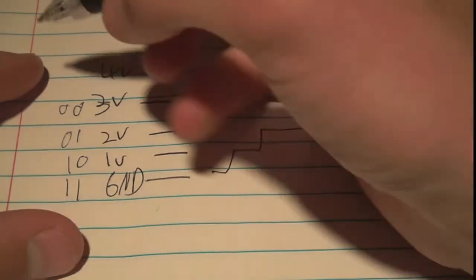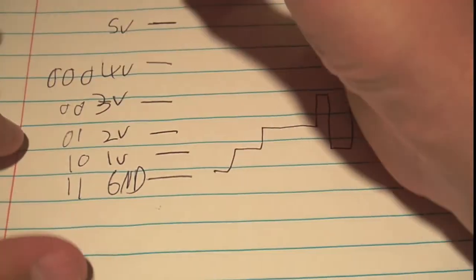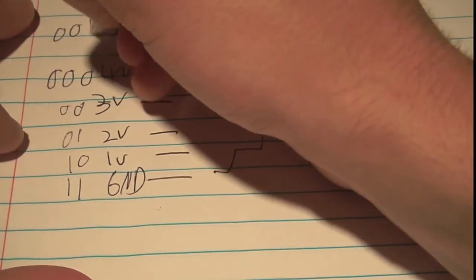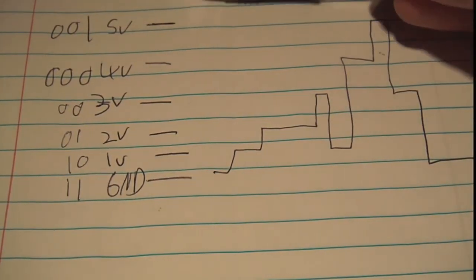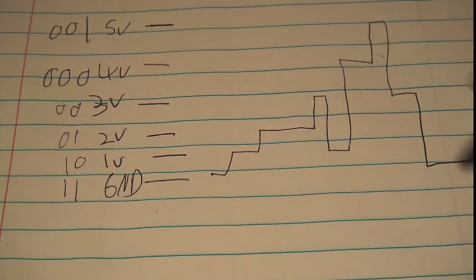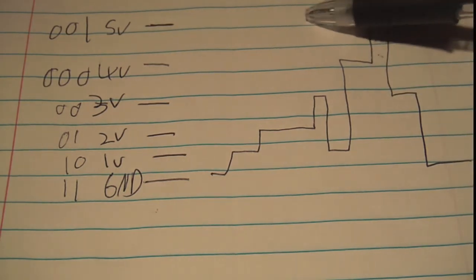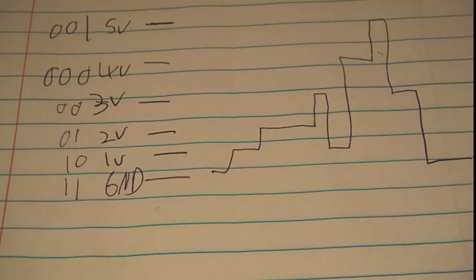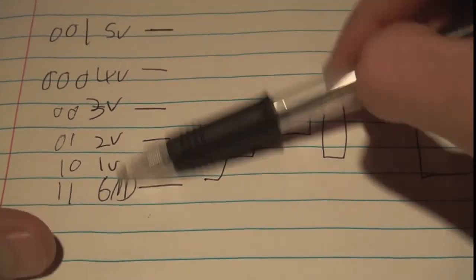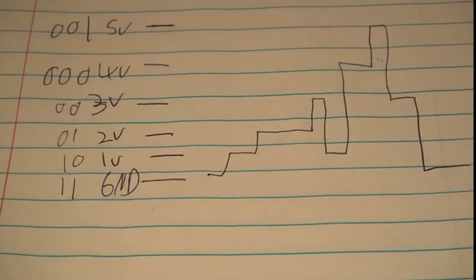And then past that, you can start going 0, 0, 0, and then 0, 0, 1, right? And then you would have to keep going and going. But using this multiple signal system, you can actually split it up to increase your bit density and thus increase your bandwidth, because you're actually sending more data in the same signal because you have multiple levels, and so each level can mean twice as much.